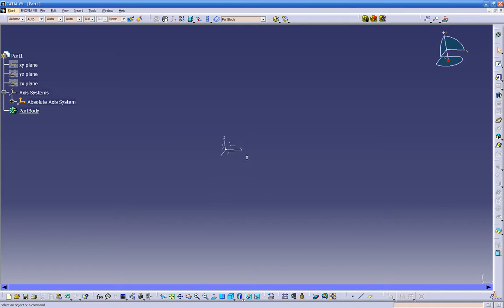Let's play more with the Sketcher, learn a couple more things, how to build some rectangles. So let's go back on the Sketcher. See, once you click on the Sketcher, it's going to ask us to select the plane, or the planar face, or the sketch.